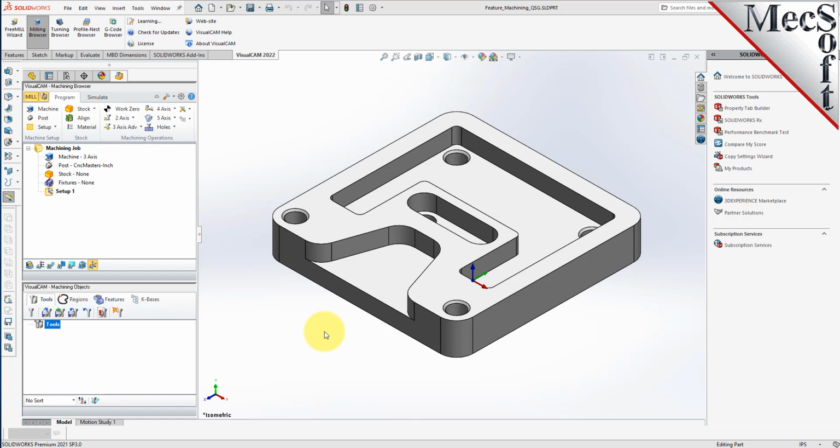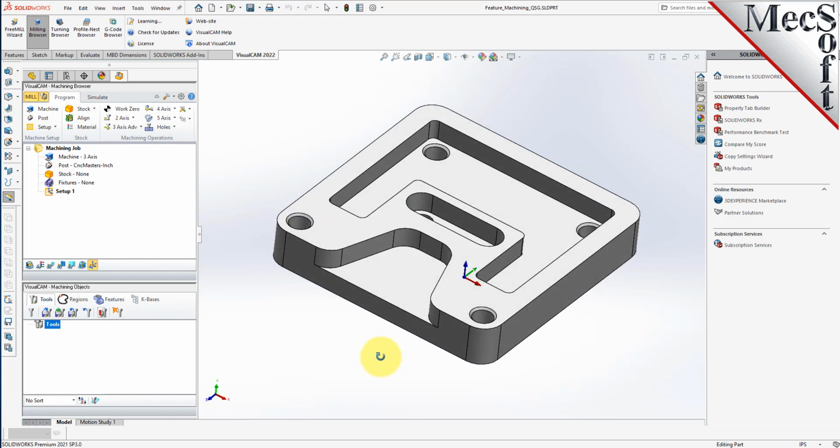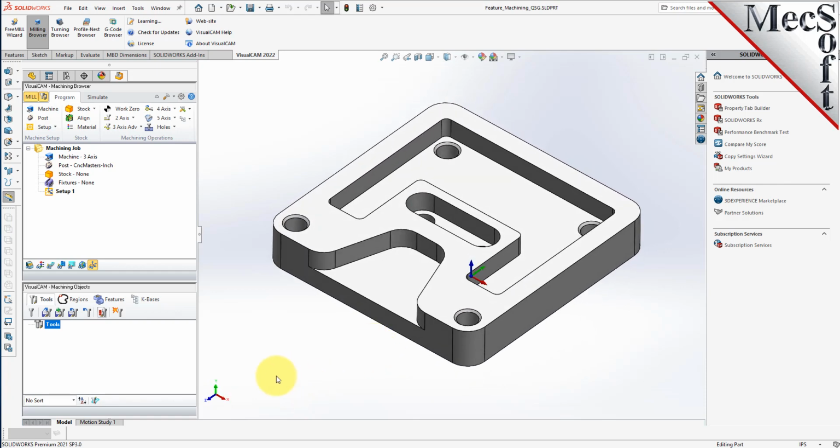Now, there are just two requirements for AFM. The first is that you have to have a solid model. It can be a closed polysurface model, or a solid model that you imported from another CAD application or created. And the other is that you need to have a knowledge base created that has the definitions for each of the toolpaths that your part features contain.